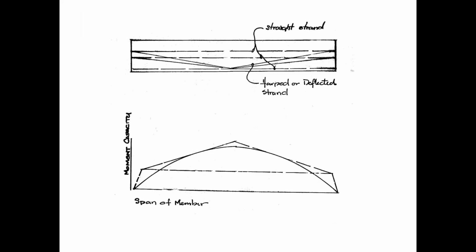And the moment in a beam, which is kind of an odd term, is depicting how the energy in the beam is distributed as that beam is resisting an applied load. Generally, if we have a beam that just has a uniform load across the length, think about a bridge girder with cars on the bridge, bumper to bumper, rush hour traffic, so you've just got a uniform load along the full length of the span.